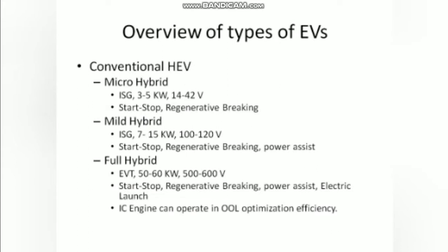This is known as the start-stop feature, which can be provided very easily in electric vehicles. These features enable fuel economy in these vehicles, as they can also help in recovery of regenerative power available during braking. Generally, this is a low power ISG and it is connected using a belt driven system.